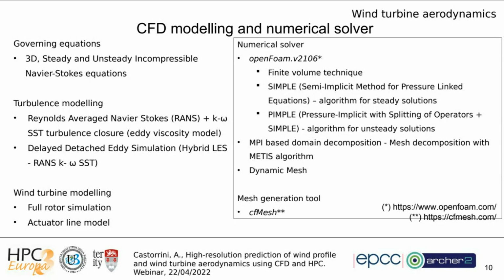About the tools that are used for the simulation. We use OpenFOAM as the CFD solving library, which is already present on ARCHER2. ARCHER2 is the machine where almost all the computations have been done. This library is based on the finite volume technique for the discretization, and it adopts the SIMPLE algorithm for steady solutions and the PIMPLE algorithm for unsteady solutions.